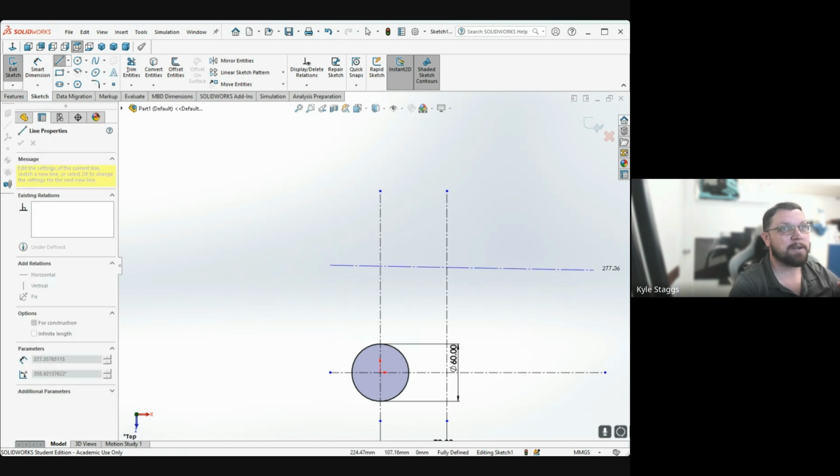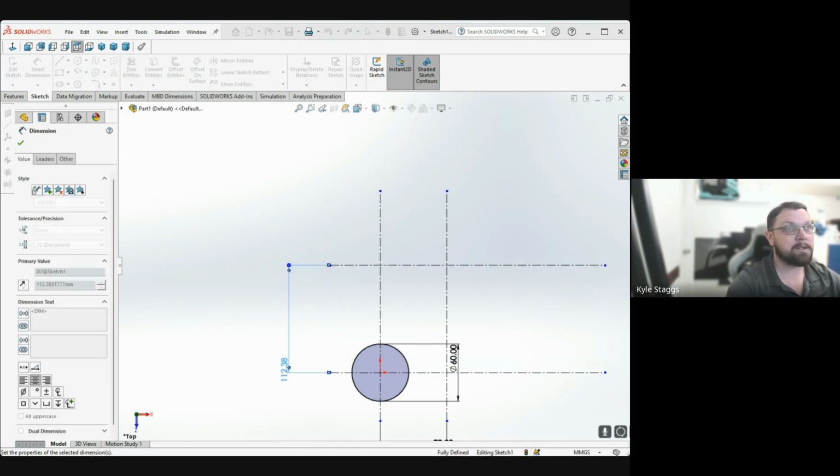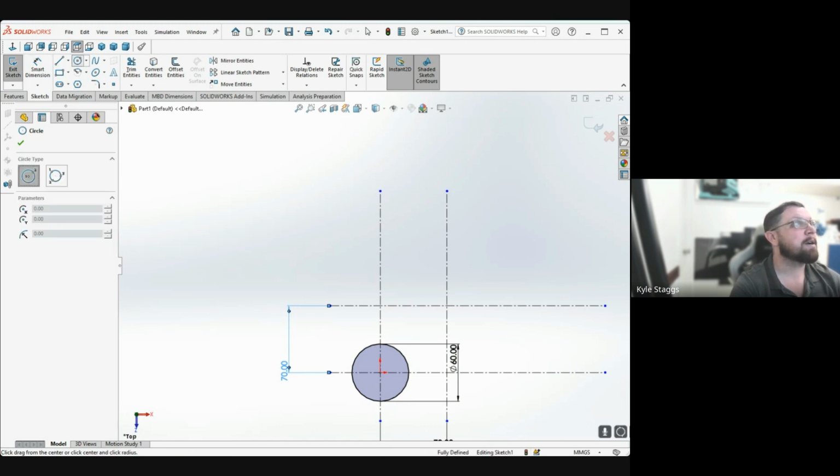We're going to need another center line. And because we want this to be what's called a square pitch, you guys are learning all kinds of things today. A square pitch reference means the whole spacing, center to center, is the same in each direction. So it's the same in the X and the Y. A square pitch is often used for things like heat exchangers, like intercooler bar and plate spacing, some of those sorts of things.